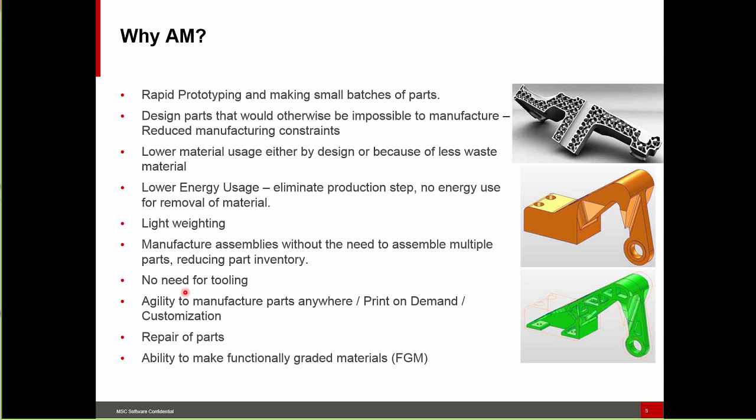Another advantage of additive manufacturing is that it allows us to manufacture parts that we could design but previously could not build. So we could use topology optimization. We could come up with very creative designs, interesting geometry, but you actually couldn't manufacture the part, or, using casting, it would have been very difficult to manufacture the part. We can see that it reduces the amount of material being used, either because of this innovative design process or the fact that we are adding material as opposed to subtracting material, and we're saving material waste.